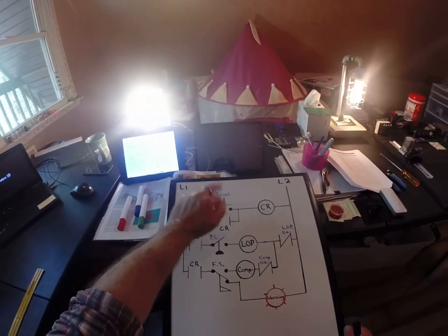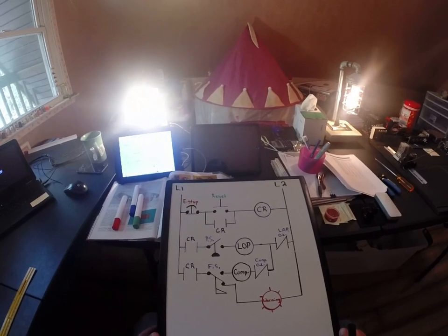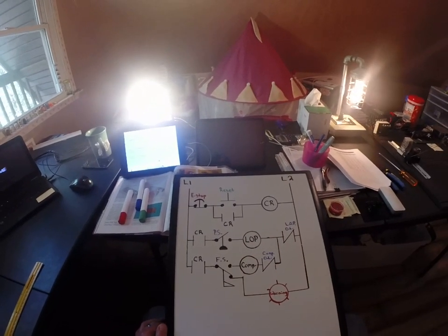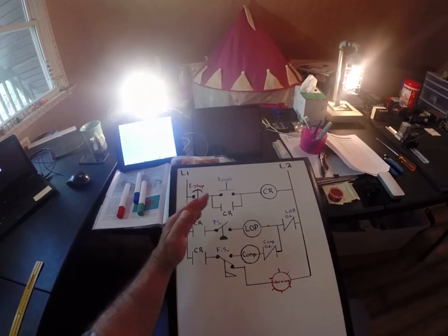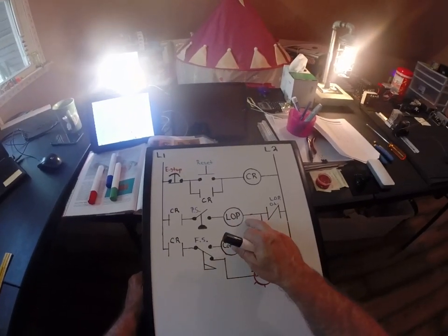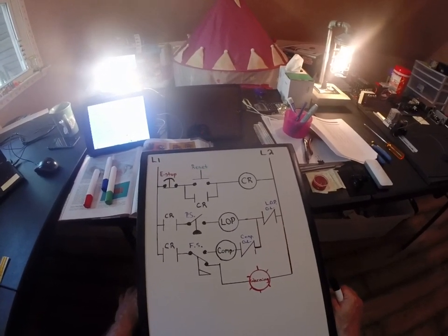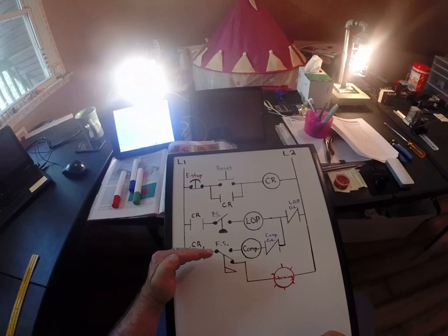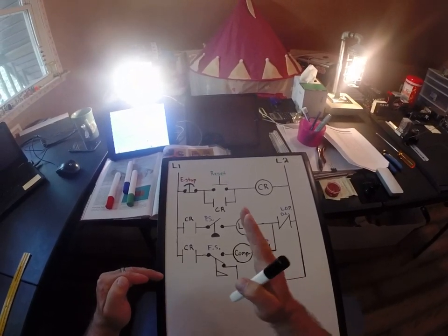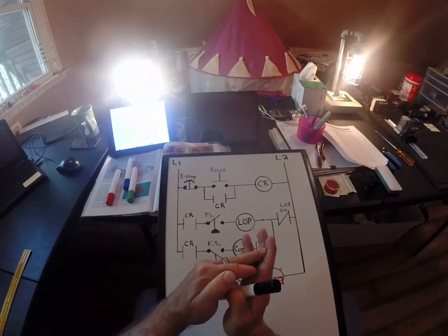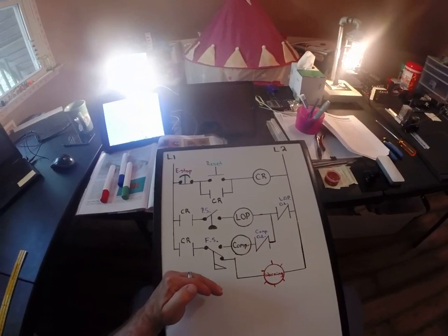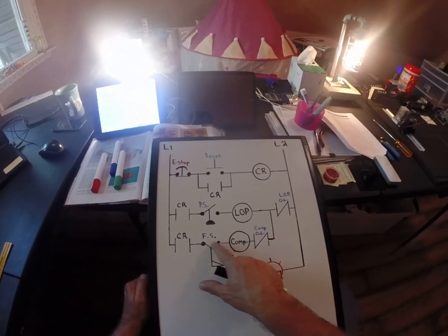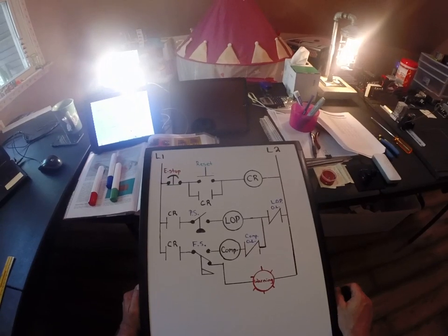We go in, we hit the reset button on the machine outside the gas station. CR becomes energized, that closes, that closes, that closes. We get a drop in pressure, allowing that contact to close. Then it energizes the lube oil pump. That pump starts to pump oil. Once, remember, this contact is closed, the oil's pumping. Once that oil flow hits the switch, it'll close this switch. Right now it's hearing the alarm, but it'll close this contact, energizing the compressor.